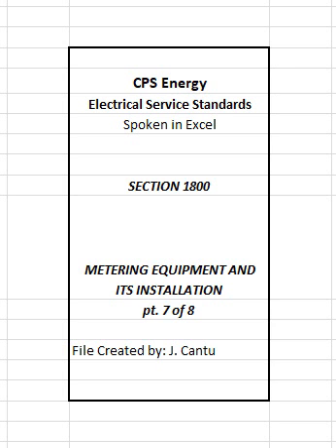Customer must furnish and install conduit hubs or equivalent devices on auxiliary meter gutters. On outdoor installations, all such devices must be weatherproof. Conduit hubs shall not be installed with self-tapping screws, machine bolts are required.